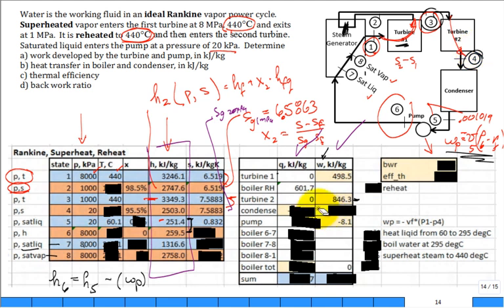All right, condenser. No work done in the condenser. No pressure change in the condenser. It's just heat transfer in the condenser. It comes in with relatively high, exits low enthalpy. So the difference is going to be the H5 minus H4 because you get the negative out. Or it's a negative in, which is an out. So I'm trying to stay consistent with the numbers, positive sign and negative sign in the textbook.